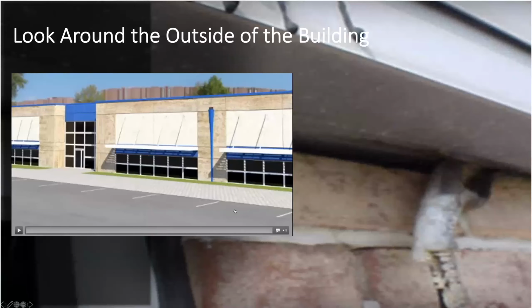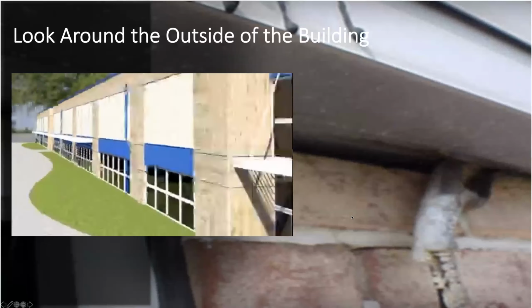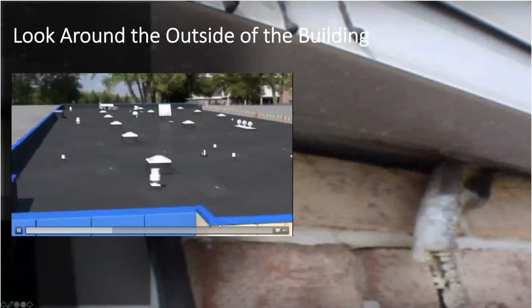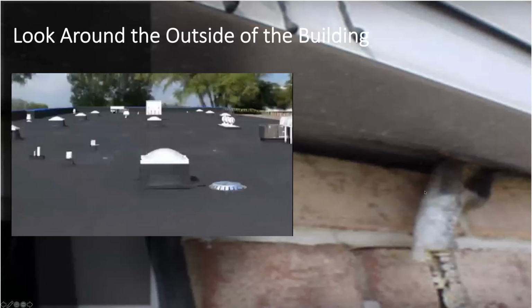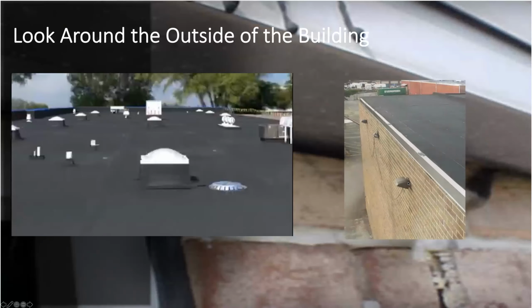After that, we recommend starting on the outside of the building, taking a look around the perimeter, which sounds odd, but a lot of times control joints, different components, these panels, things like that can fail and cause issues. And a lot of times the roof is blamed for it. What we see, like here, a coping cap that's been knocked off and continues to lift. Once on the roof, it's good to take a good look at this to see how much damage is here and how it needs to be repaired.